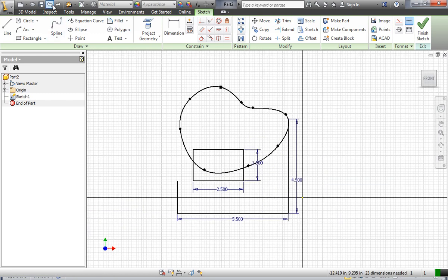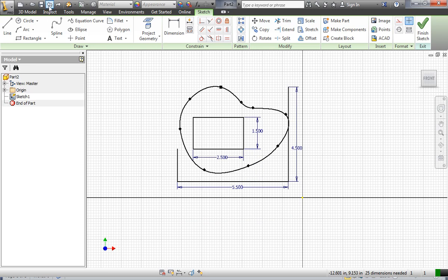What I'm going to do is go back, use the back button, and delete these dimensions. When the line is dimensioned, sometimes, well, every time, when you start trimming things off, it keeps that dimension there, and that could have an effect on the part. So I'm going to delete the dimension, and that way I can change the lengths of the lines or get rid of them freely. I can also just click on the line and delete it without trimming it.